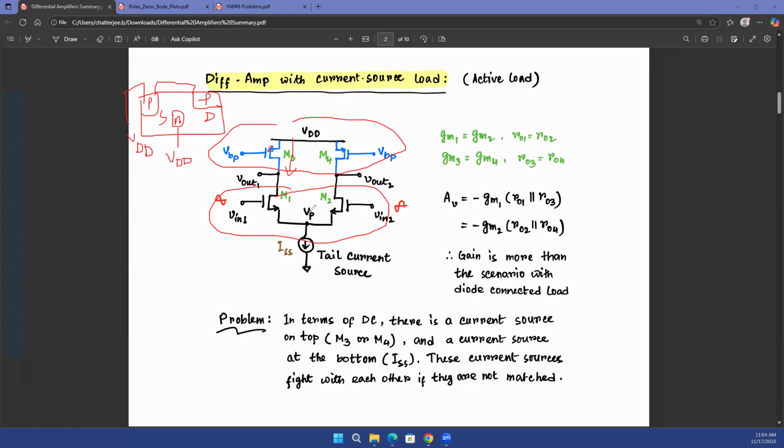So you can do that. Also, we'll learn about another reason when we start discussing CMOS digital circuits. We'll learn about that reason as well, but at this point, this is one of the reasons why we keep PMOS on top and NMOS at the bottom. If you had put NMOS on top, the problem would have been there would be two NMOSes stacked.